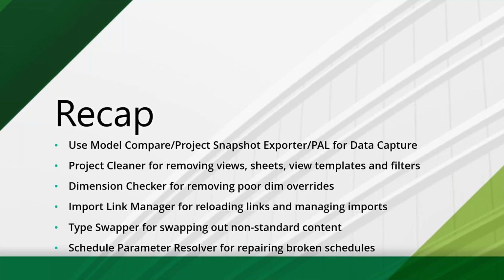And I didn't have room for it, but we also talked about the Revision Manager and Revision Cloud Remover to assist with revision management during the CA process, and to help clean up revisions that were showing on sheets that shouldn't have been on the sheet, right? Especially if things were hidden and issued. It's hard to track things down without a reporting tool. So we used both the Revision Manager and Revision Cloud Remover to do some cleanup on that front.